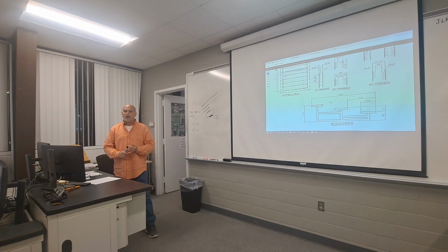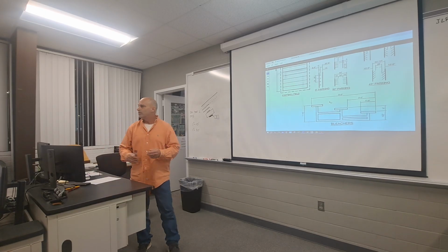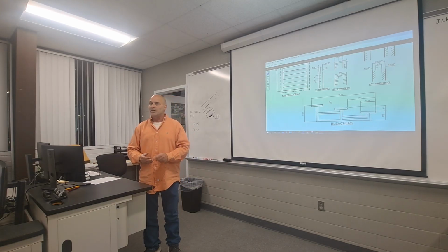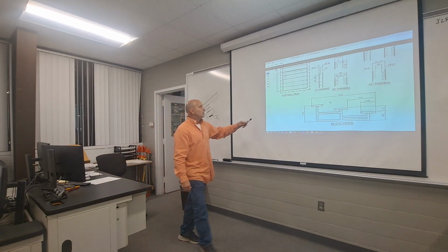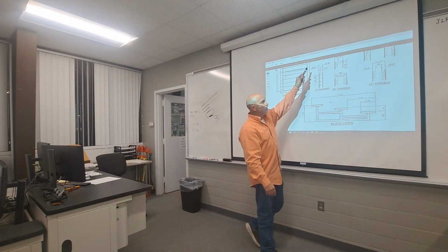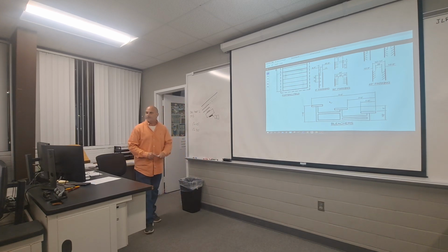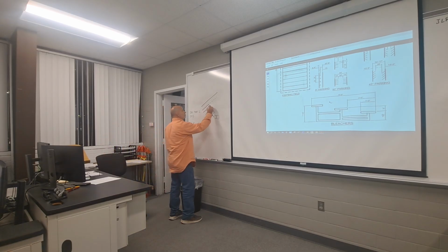We're gonna talk about the parking lot in a moment. You're gonna be bringing a 5-foot sidewalk from your parking lot, 1 or 2, 3, whatever works best for your project. And at some point, it's gonna branch off or go to each one of these items. The football field and any basketball or tennis courts that y'all have will need a sidewalk accessing it. Those sidewalks need to be 5 foot wide. That is ADA standards.